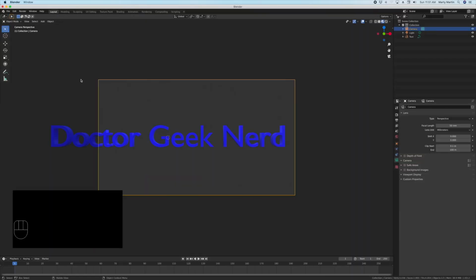Let's zoom out again. There we go. Not great, not centered, but the camera is selected, so I can hit the N key to bring up the number panel. And let's see, I want to move it to the left a little bit. So if I click and drag on the X location, I can drag it to the center, and it is too close. So I want to move it back on the Y axis. So if I drag around the Y-axis there, I can reposition that. Okay, so that's the view that's going to happen when it's rendered.